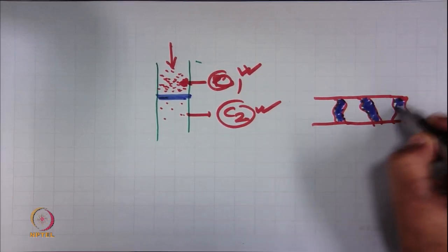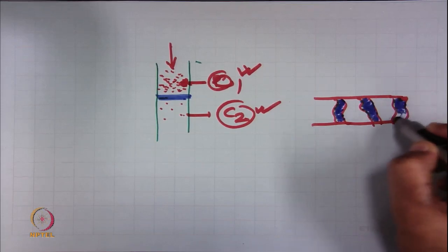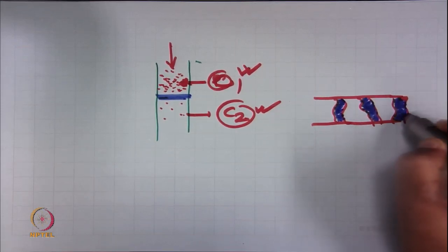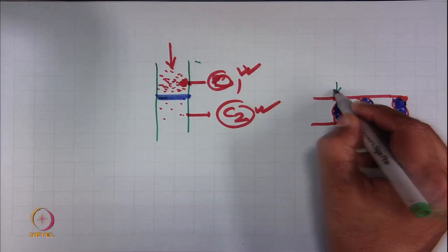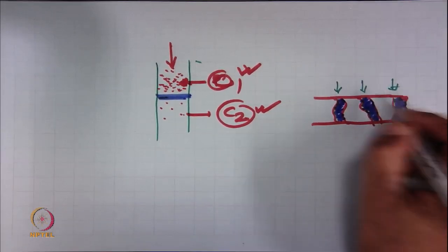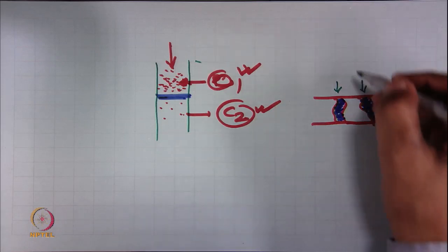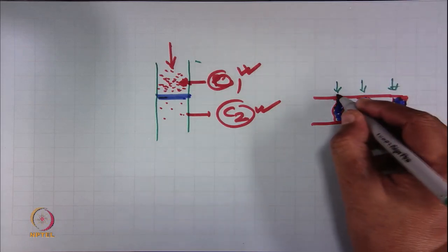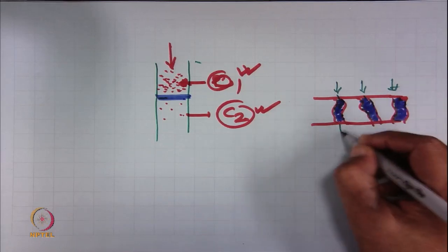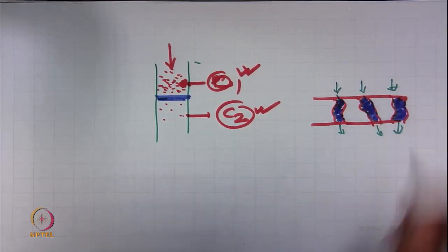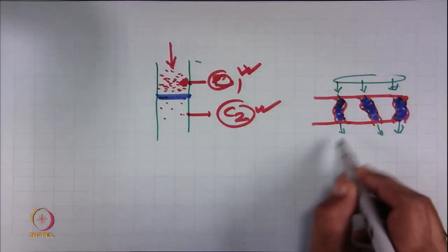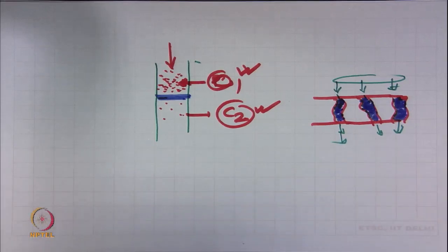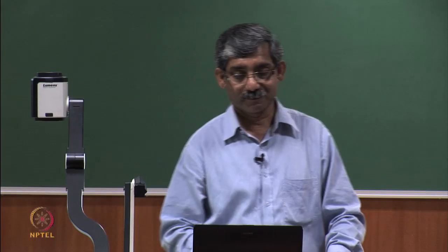Once the filter medium is wet, then the inert gas is forced through this filter medium, which will force the liquid out of the pores, and we measure the pressure and flow rate. From this data we can calculate the pore dimension.